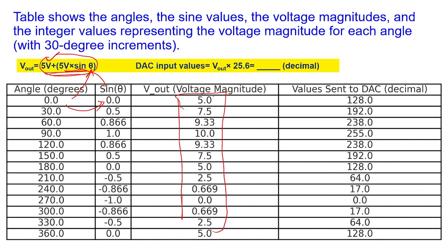Now I'm going to do the scaling factor. We know it's 2 power 8, since it's an 8-bit DAC, so 256. The 10 volts, +5 and -5, maximum of 10 volts, you can represent by 256. Suppose I want to represent 1 volt, it should be divided by the scaling factor of 10. You will get 25.6. This is for 1 volt.